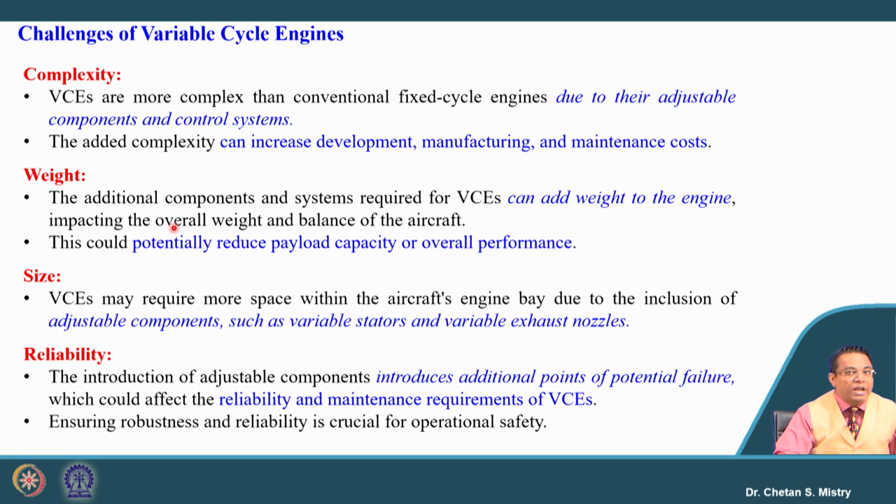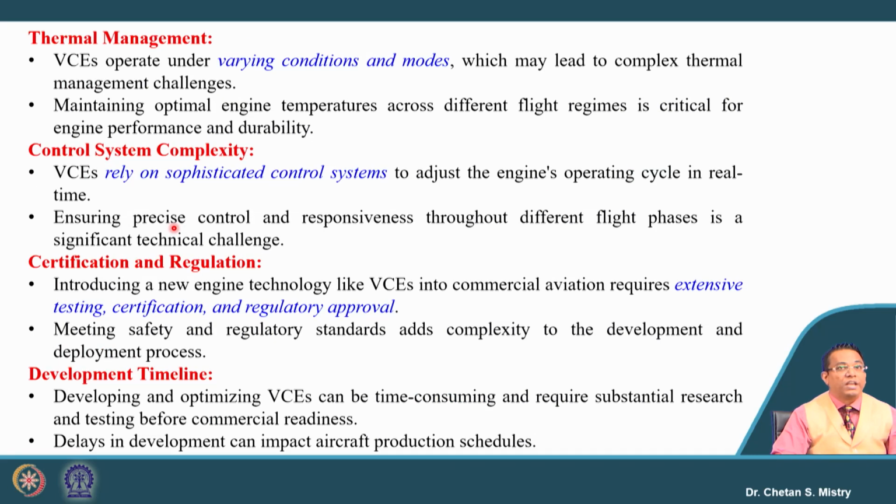The size of this engine is higher because it has special kind of control mechanisms and devices like variable stator, variable exhaust, all those things. That will be increasing the size. At the same time, because of the incorporation of these devices, reliability of this engine is a question mark. Also, since our operating temperature is higher and it is operating under different modes and conditions, that puts more challenge on thermal management.